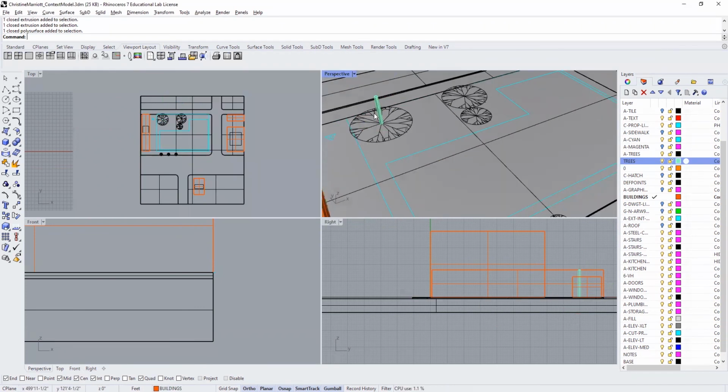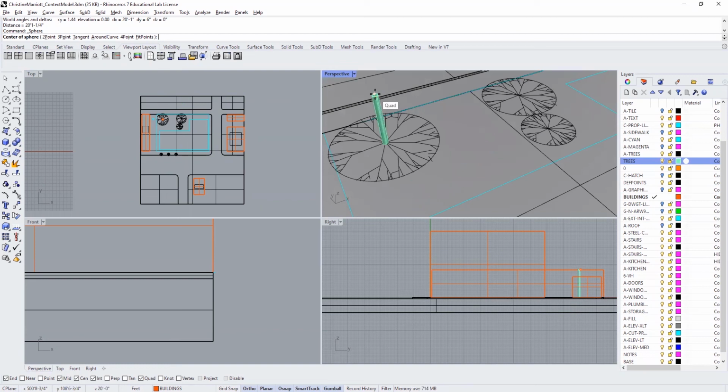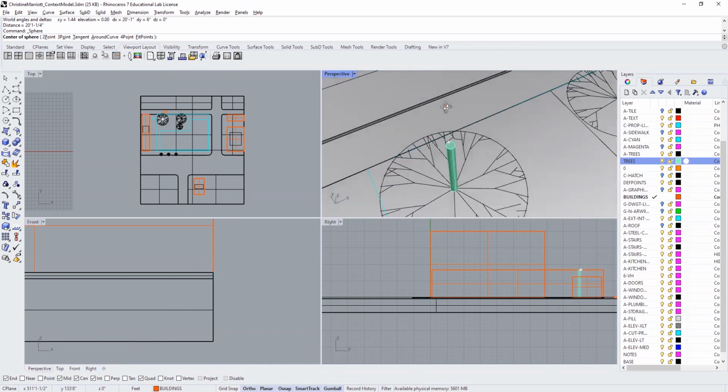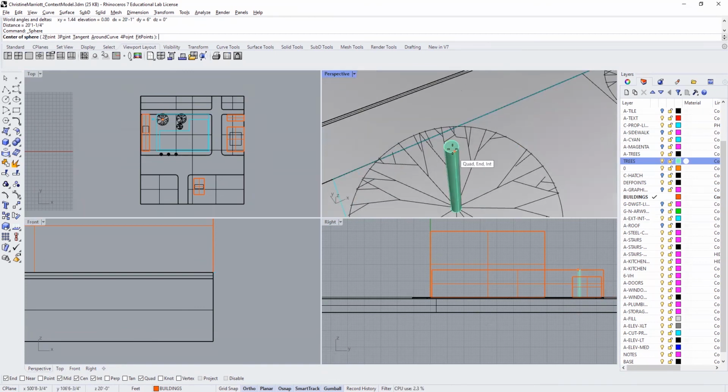Okay, and then on top of that, perhaps make some kind of sphere. So using the same primitives, the sphere tool. Before I do that, let's check that the diameter or the radius, about a 20-foot radius. So I will temporarily place it at the center of the top of the cylinder. Type in CEN, so we force it to go to the center.